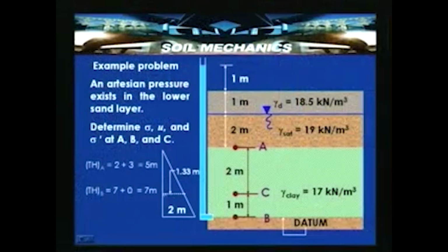So, here at point C, the total head which is available, the energy delta H, is HB minus HA, around 2 meters. At this particular point 0.67 meters of the head is already lost. That means that now 1.33 meters of head is available to be spent in enabling the flow to take place through the soil.